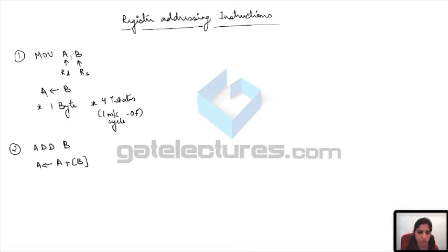Any other register also. So better to write R here. Any general register, B, C, D, E, H, L, whatever you are giving in the instruction, it's going to add. This is going to be any register. So this is also a 1 byte long instruction, and only opcode fetch is going to take place. Fine. And also we know that flags are going to be affected for every arithmetic operation. So according to the arithmetic operation that you're performing, flags are going to change.